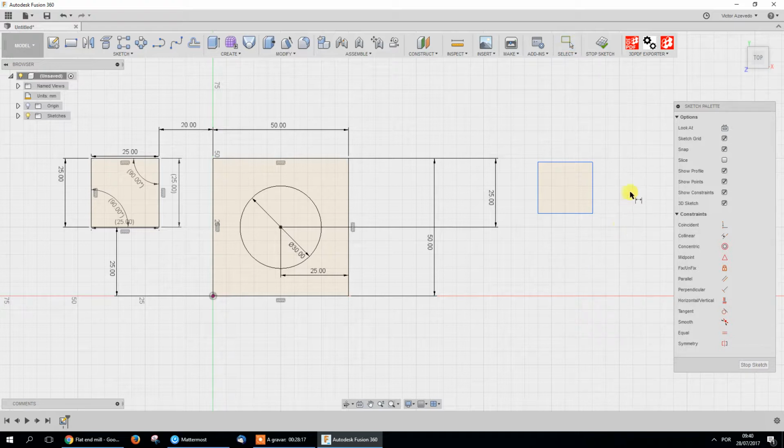Use dimension. From this one to this one, instead of 90, now it's not driven. I can change it. Let's say 120. And now I have an angle. Since it doesn't have any constraints on the sides, it will change as it wishes.